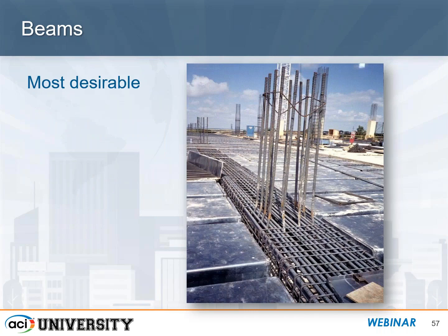So here's a nice example of that. Again, this is a wide module joist system. You can see the pan forms here. The rebar is all set for the girders that are going to be supporting this joist, and you can see you have a lot of breathing room here to space this relatively heavy top and bottom reinforcement that's going through the joint. Now keep in mind,